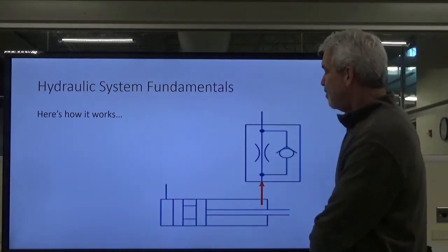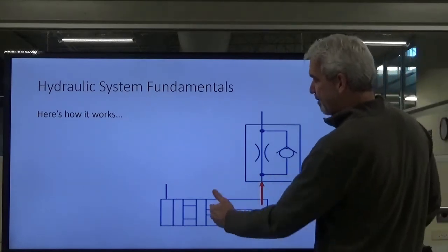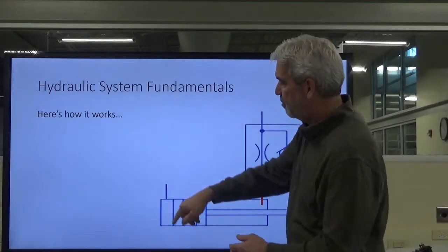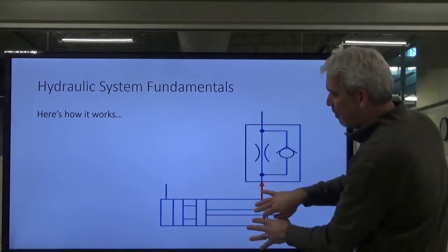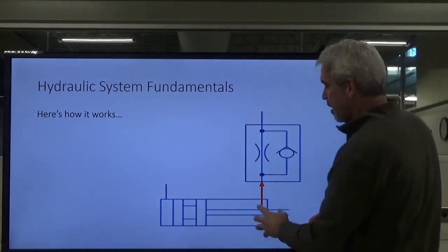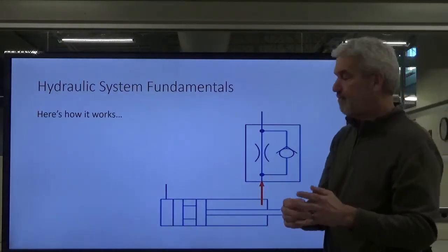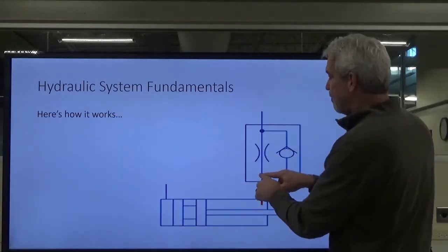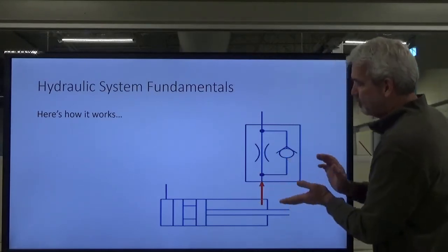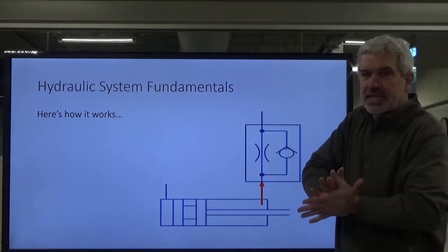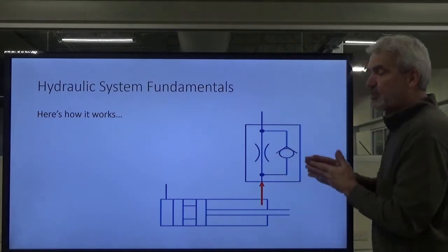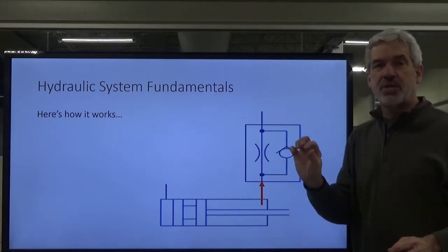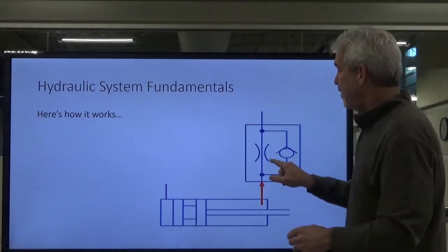But if we put that same valve on the exit side of this for the fluid on this cylinder, and we have our oil flowing through here, okay, we're pushing our cylinder this way, all the oil on this side of the piston is trying to evacuate, and we are forcing it into our flow control valve. Now, the oil can go one of two places, just like we showed you earlier, all right? However, when it chooses to go this way, it's back behind that ball, and we're just further seating that ball into its seat. So it's fully blocking it, and it's forcing all of the oil to go through our metering section so that we can have full control of the flow, okay?